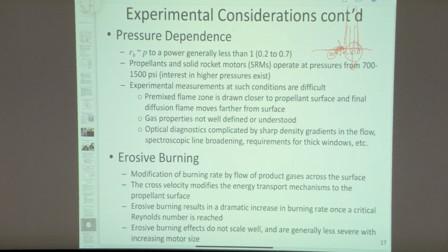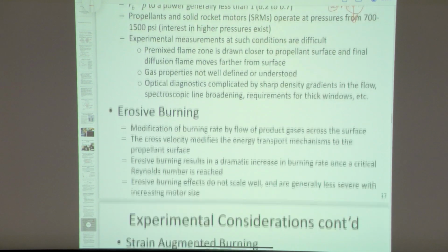Gas properties are not well defined or understood at very high pressures, and optical diagnostics are complicated by sharp density gradients in the flow, spectroscopic line broadening, and the requirements for very thick windows. I told you the windows in that chamber I just built were 4 inches thick, so you've got to worry about those characteristics as well.